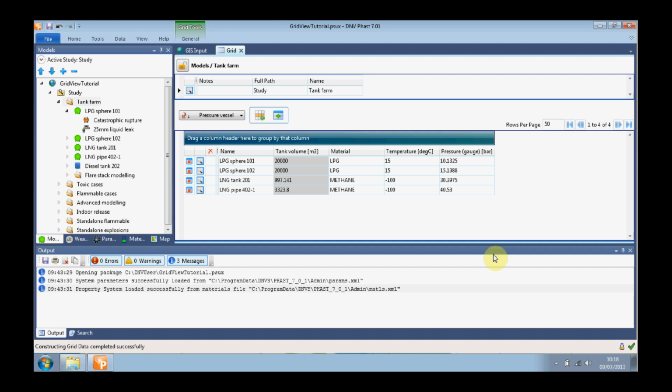The data may also be altered and added to in Excel to be copied back into Phast. This is useful because it means that analyses can be conducted on a large range of scenarios without having to create individual scenarios in Phast, which can be time consuming. So we will now explore, for example, how changing the orifice diameter of a pressure vessel leak affects the results by adding and editing new leaks in Excel and increasing the orifice diameter in small increments.